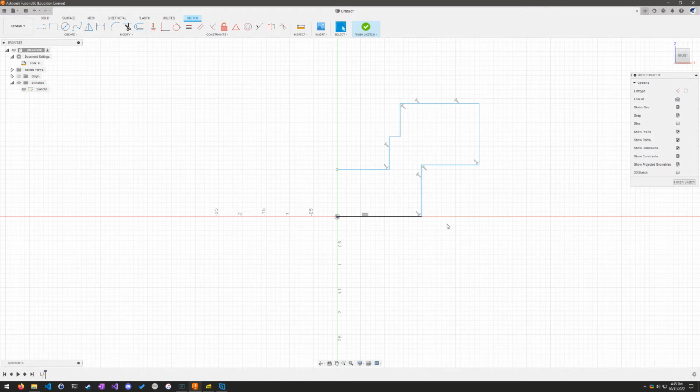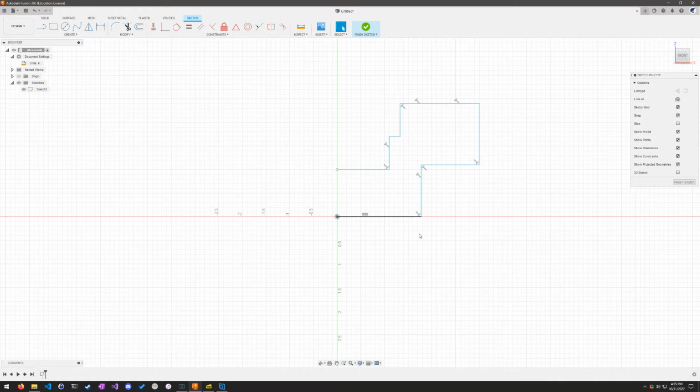It'll come with experience. So the rest of the lines are blue, and we need to get our red padlock back, right? Remember we had a red padlock? Now we have a pencil. We want that pencil to go away. And the way to get that pencil to go away is to start dimensioning.